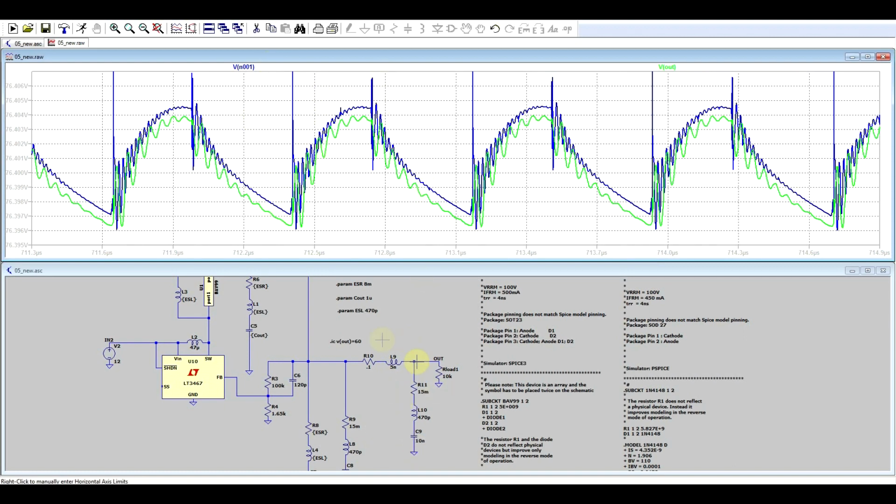It will be filtered out by the trace and local decoupling capacitors. Now the amplitude of the lower frequency noise has remained unchanged if the decoupling capacitor is small. If this would be a bigger capacitor, say another 1 microfarad capacitor, then the output would look completely different.